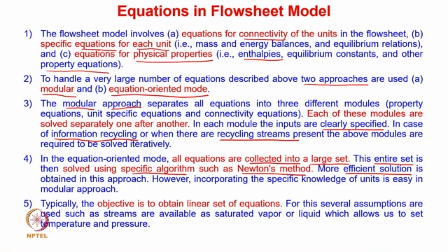But the drawback of this approach is that it is more cumbersome, because you are solving all the sets of equations together, so at times it can be computationally challenging also. And again, incorporating the specific knowledge of the units is easy in the modular approach compared to the equation oriented approach. So these are the pros and cons of both these approaches.